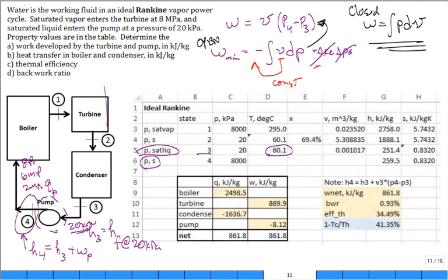Remember this. When we get to gas power systems, we'll bring it up again. And so why do you have multi-stage compressors? What happens in between the stages of a gas compressor? Intercooling. And that's to help bring that specific volume down, reduce the net work as you boost the pressure in a compressor. So this is a great concept.